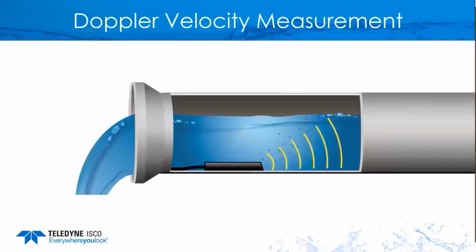But let's take a close look at using an area velocity sensor. Before I mentioned that the flow rate is calculated using area times velocity. We have a pressure transducer to read the water depth. So it will read in the open channel or even in a full pipe. So it knows if it goes 100% full, the area is at 100% and times velocity to get our flow rate. So at that point, during full pipes, it's essentially almost like a magmeter where the flow rate is proportional to velocity.